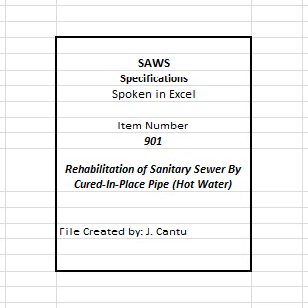7. Groundwater depth shall be ground surface at a minimum or the elevation of the 100-year floodplain water surface, whichever is greater, in order to account for all reasonable anticipated future loadings. 8. Long-term flexural modulus retention, 50%.